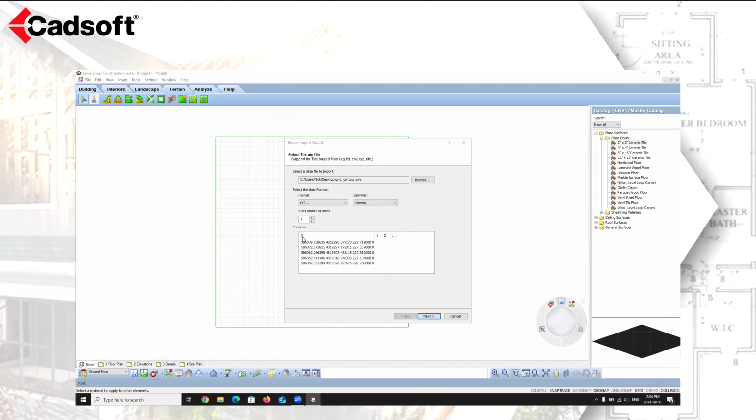So I should be seeing points in the X, in the Y, and the Z. If you don't know what it is, you can simply just click through and it should update for you. And then as soon as you find the one that moves everything in the correct format, that is the actual delimiter. And again, as you can see, as I go through all of these, none of them work or show me the correct way until I get the space.